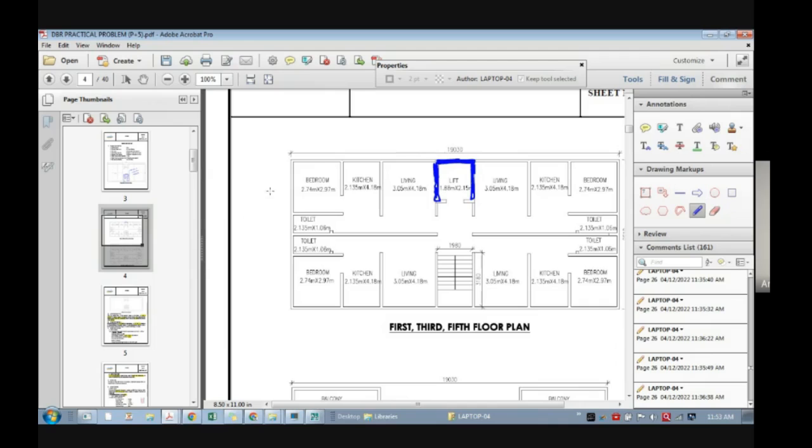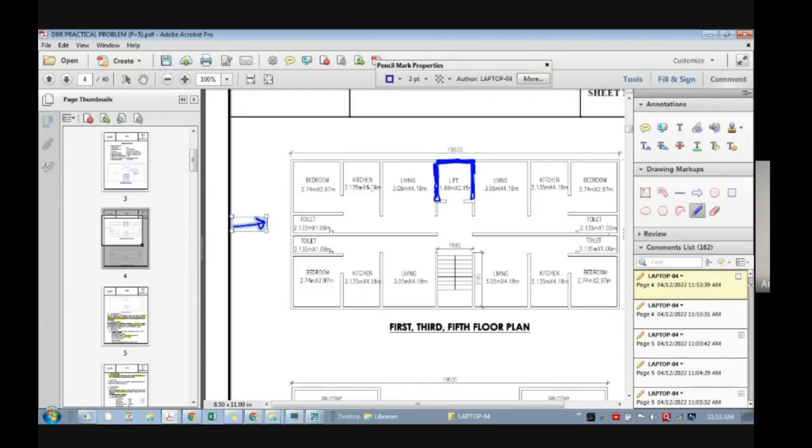Now, let's say there is earthquake load in this direction and your building is not taking the earthquake load, or the deflection is more due to earthquake. Then you can add some additional shear walls like this. By looking at the architectural plan, you can suggest the locations. So the number of shear walls and length of shear wall depend on the earthquake force.